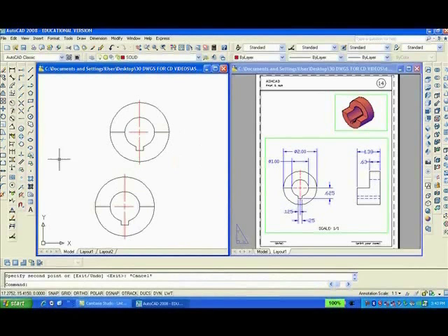What I'll do is type BR enter and simply break that two places and break this two places. Now what I want to do is trim from these two lines, enter, all these excesses, make two parts out of it. Okay.